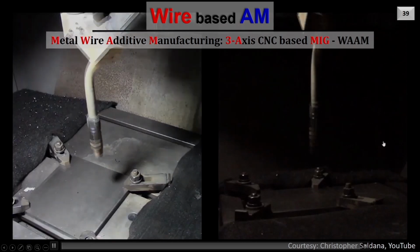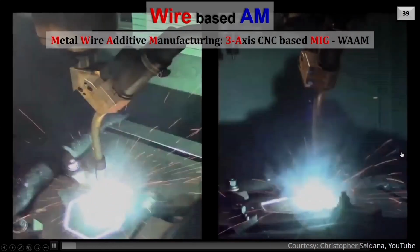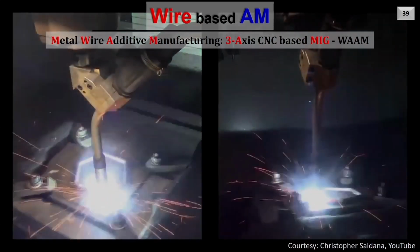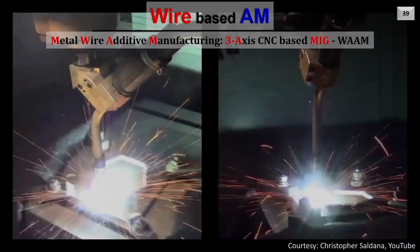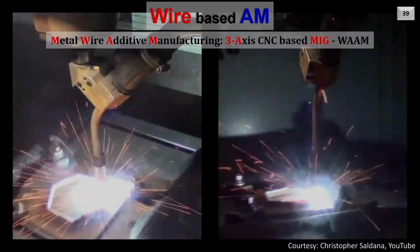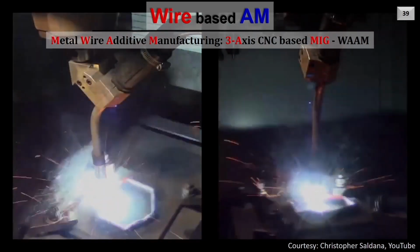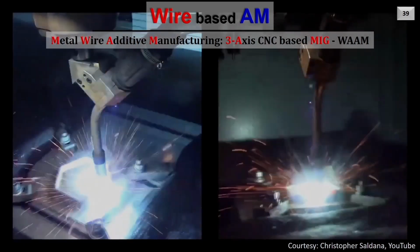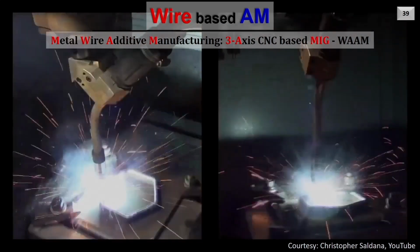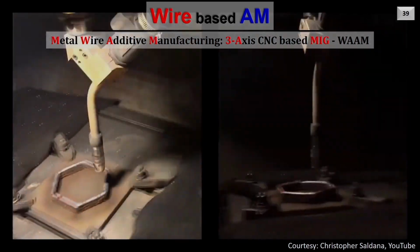So this is the video for an example of 3-axis CNC based MIG welding WAAM. In this case, you can see the MIG welding gun is mounted on the spindle head of a 3-axis CNC machine, and it is depositing the material on a substrate. As the gun cannot tilt in this case, it can be noticed that there is no possibility of realizing overhanging features. Of course, a very small amount of overhang can be obtained because some amount of material can be sustained due to the surface tension of the deposited material.